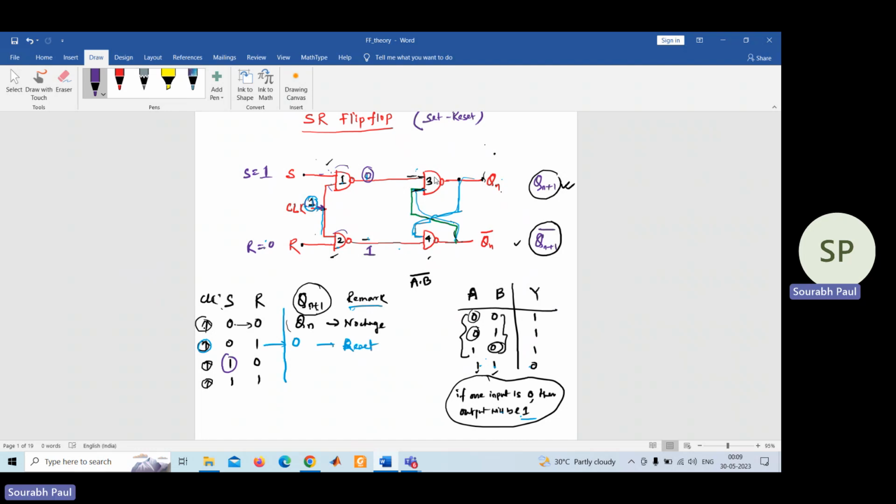Okay. Now see for NAND gate number 3 what is happening. One of the input is 0 as we have got 0 from the output of NAND gate number 1. So that 0 is applied to the input of NAND gate number 3. So as the input is 0, what output you will get? As I told, if one of the input is 0, by default its output will be 1. And this 1 is coming back here. 1, 1 becomes 0. So what we have observed, if you have given the combination of 1, 0, we have got the output of 1.